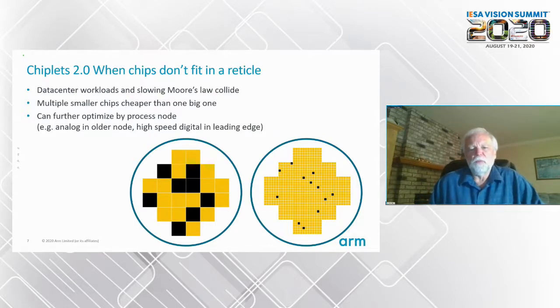So if we build a wafer and it's covered with tiny chips like the one on the right, when we spatter some defects on there, all those little black dots are no longer functional chips, but still 90% plus of those chips work. On the other hand, that same defect pattern on the bigger chips knocks out 8 of the 24. So that's only 2/3 yield. So eventually the yield hit from making chips so big limits your production, even before you get to the reticle size.